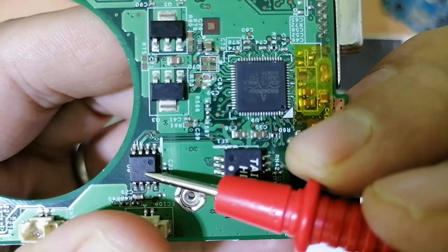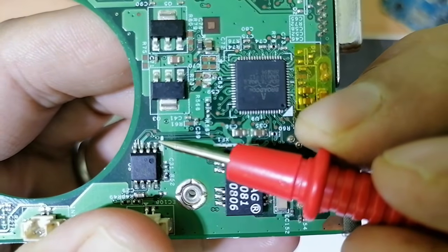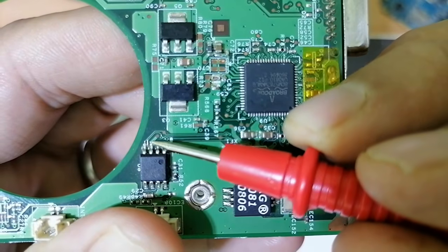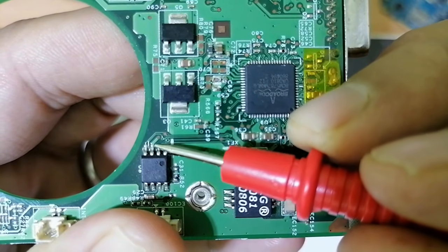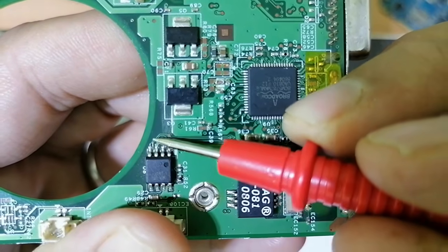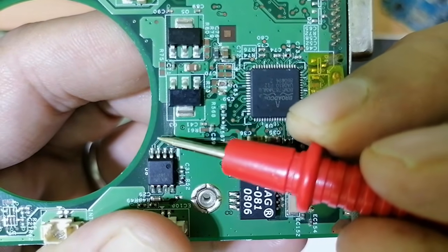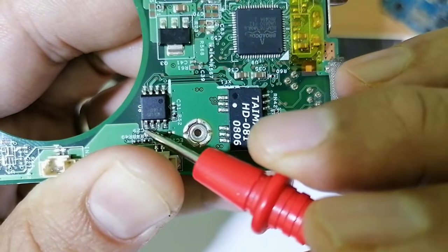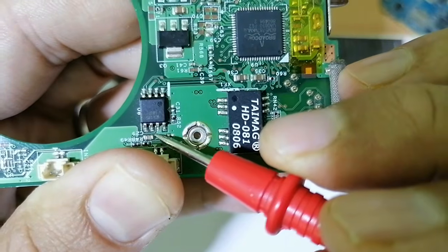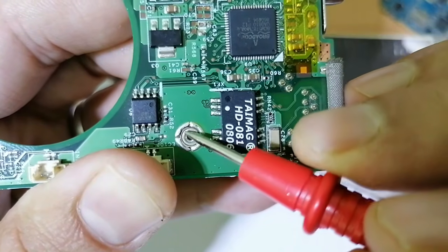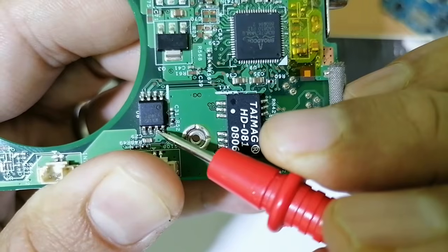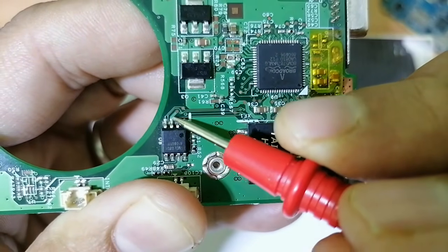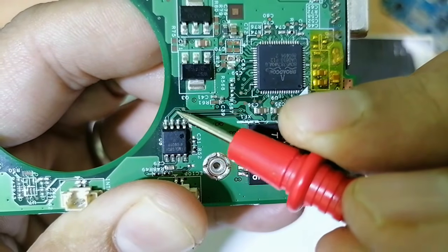Do you see? This is basically an IC, not a MOSFET. Here we have a thin pin. Here we have a thin pin. Do you see a bolded line? Means this is the input power. It could be 5 volt. And over here we have, as you can see, a thin path. If we go here also, we have control signals, and we have this bolded part connected to this hole, as you can see, means this is the ground. This pin is for ground. This pin is for input voltage, for VCC. Why? Because we have here the bolded line.